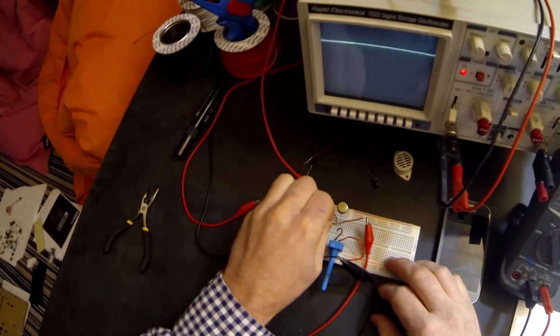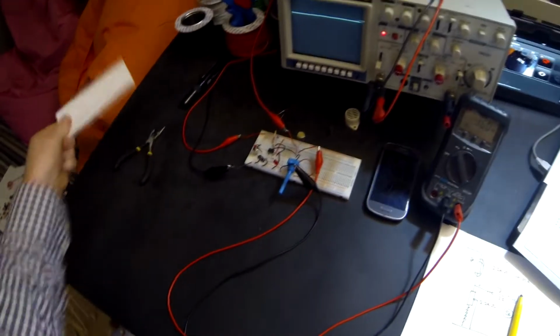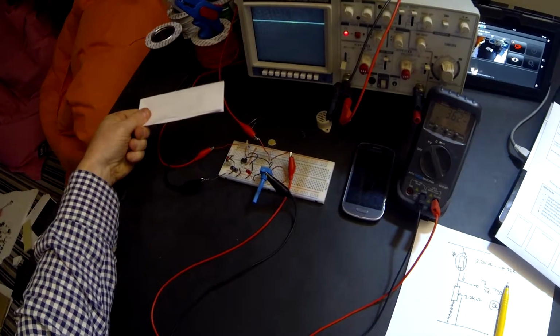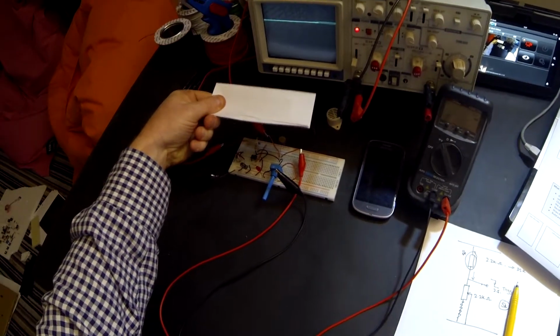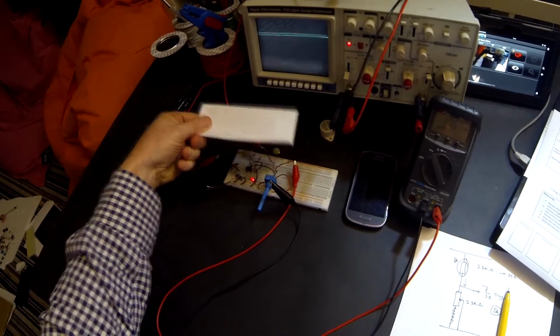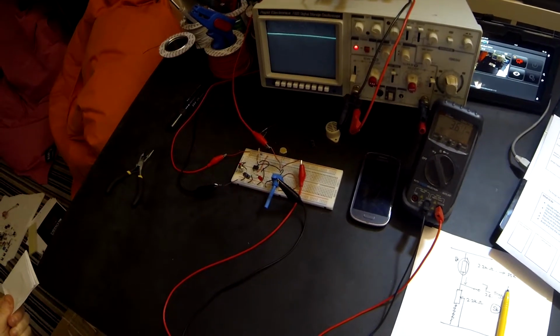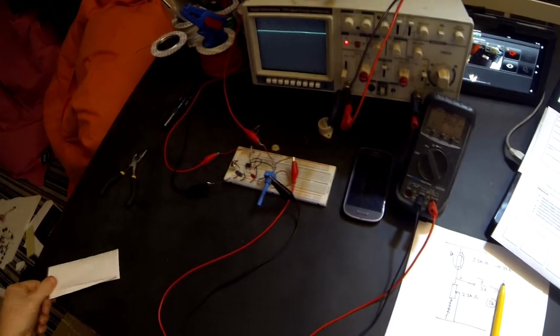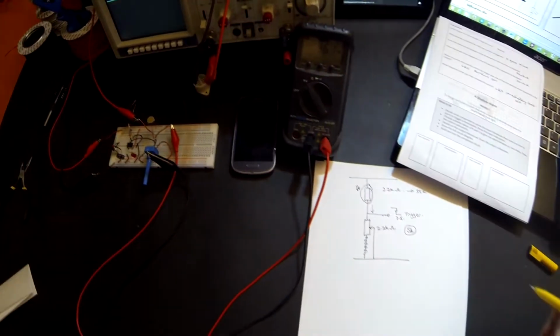So let's have a little look. Let's connect that part in, removing the switch and pull up resistor. I'm going to see, with the components that I have in there at the moment, when I cover up the LDR, does my LED come on? Yes, it does. And when I take away, does it go off? Yes, it does. So that trigger part of the circuit works well.